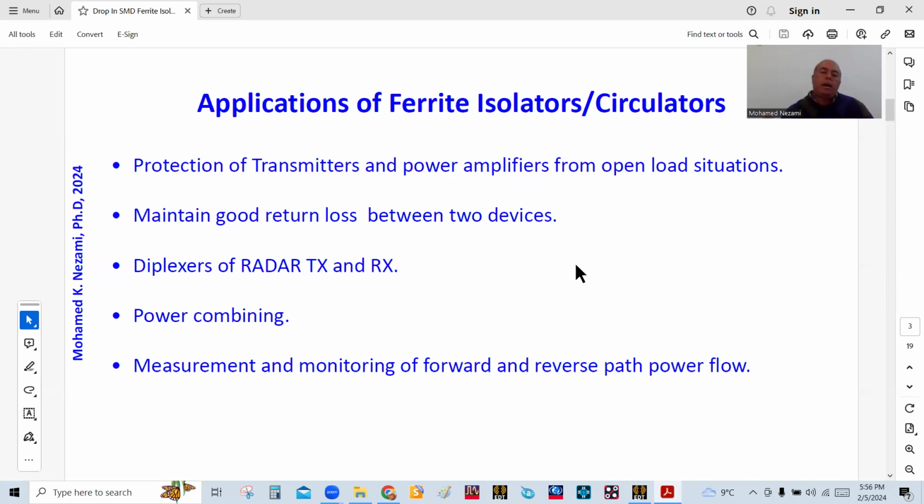Another usage of it, anytime you have a cascade of sub-circuits at high frequency, and you want to maintain good return loss between these inner stages because you can't redesign the thing, or it has a very dynamic input return VSWR. One of the ways to get around this is by doing an isolation between these interstages, by using an isolator or a terminated circulator, and that way you can actually maintain a good resistive 50 ohm, meaning good return loss.